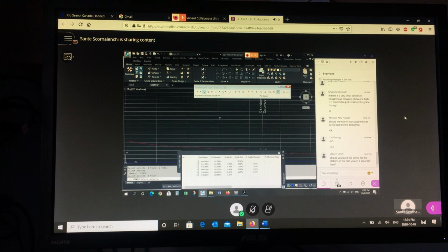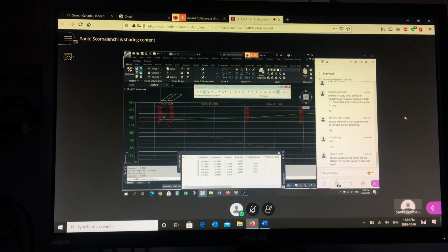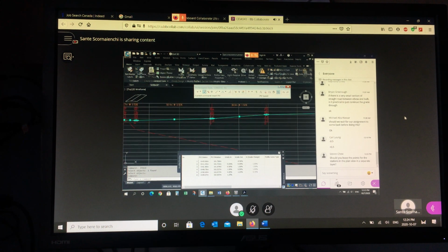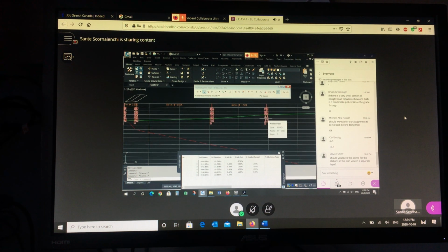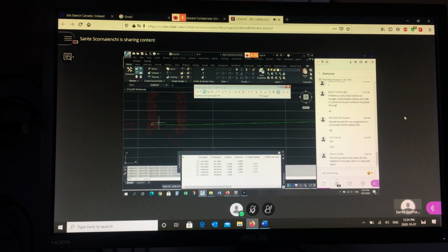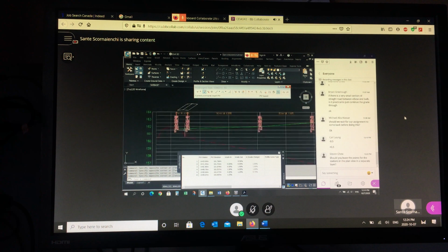Right? And then the mystery gets even bigger, right? Why are those PVI stations and elevations where they are? So when you look at this, if you didn't come to today's class, why is that station elevation there? Why is this one here and not over here? Or why is that not over here? And why are the slopes what they are? Okay? And that was today's discussion. The station value is dictated by the plan location of those key points, and then the profile slopes are coming from minimum and guaranteed gutter slopes here and here. And then this little trick at the intersection, where you have a little bit of a low point, come down half, come up at 0.5%, so that you can avoid using the vertical curve.